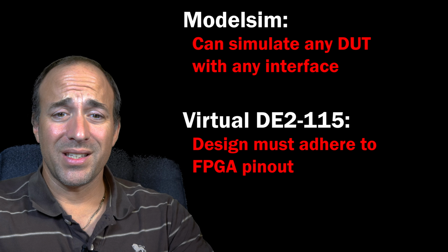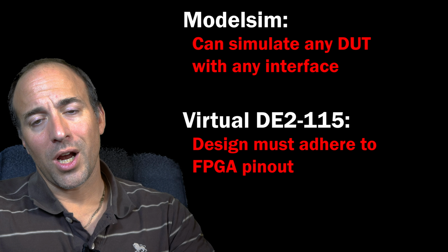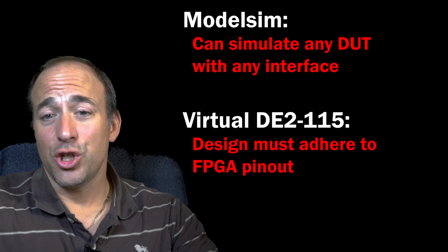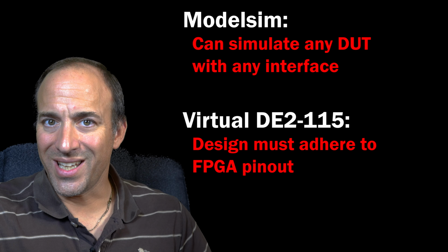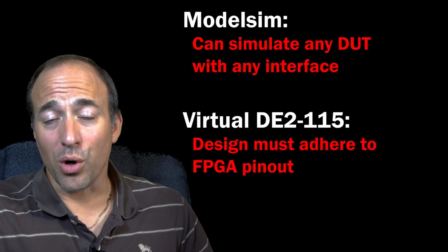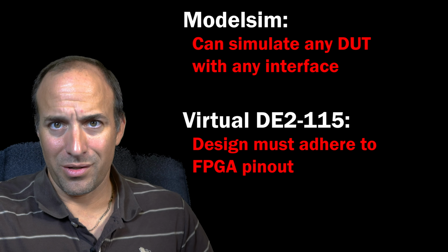Specifically, any top-level module programmed onto an FPGA in general must have its inputs and outputs exactly match the corresponding connections between the FPGA and the external components on the board to which the FPGA is connected, or actually soldered.